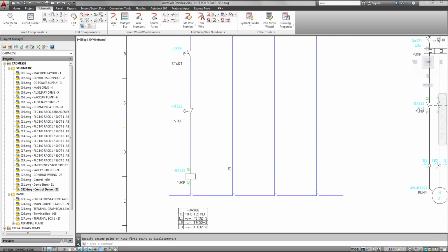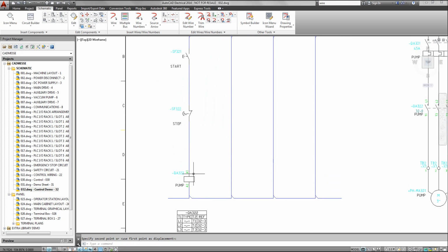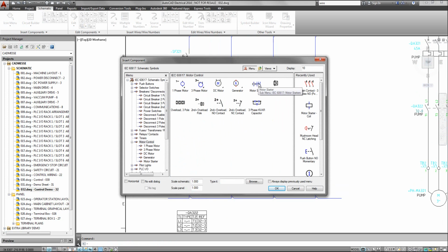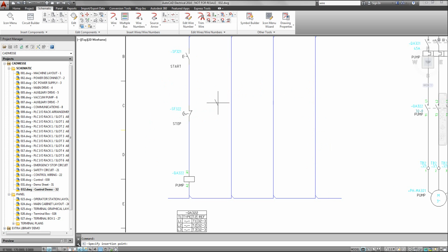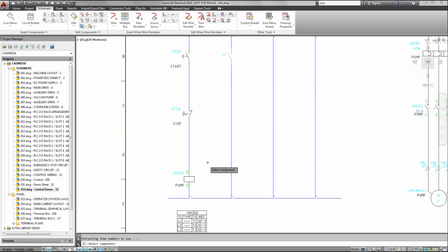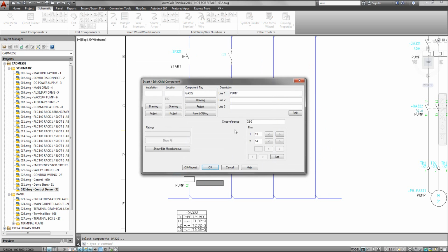And next I need to put a latching contact in for my coil, so when I hit the start button, it stays activated. So I'll go back to the icon menu again. I said we'd use this a lot. Motor control, motor starter, and I want a second normally open contact. This is basically a child normally open contact. I can drop that in there parallel to the start button. And again, I go through the process of linking them through the parent and sibling fashion.